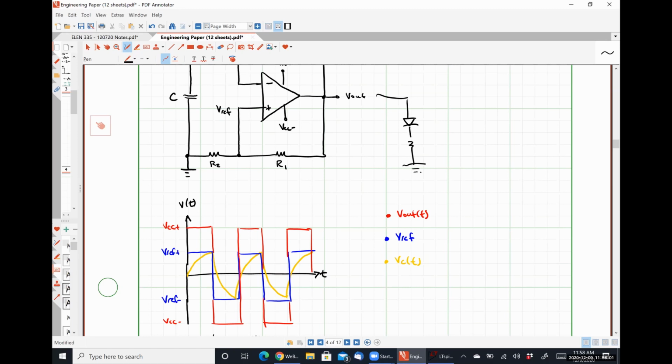Again, they're using this to drive the LED, and then they're using a photo detector to drive the tremolo circuit to effectively measure the frequency that it's oscillating at, and then use that to change the guitar signal. So anyway, it's a useful little thing. There's another group that's using the BJT version, where with the BJT version, you wind up with a sinusoid instead of a square wave. But anyway, this will show up a lot in tunable resonator circuits. So as you progress in your degree, this is a very, very useful thing.